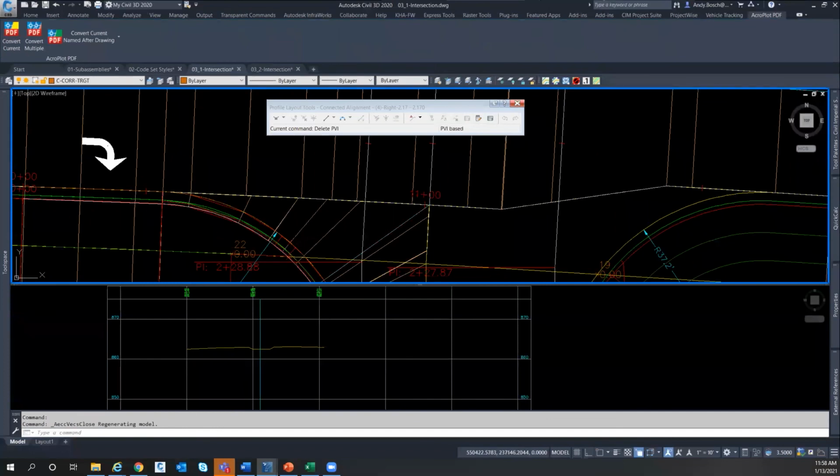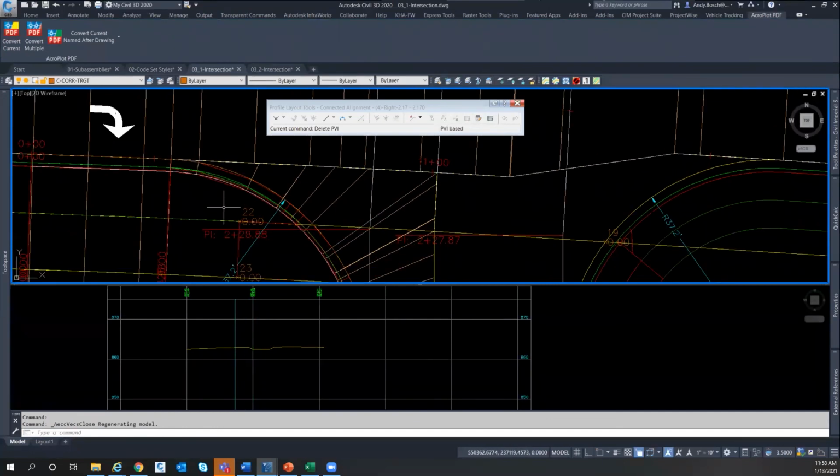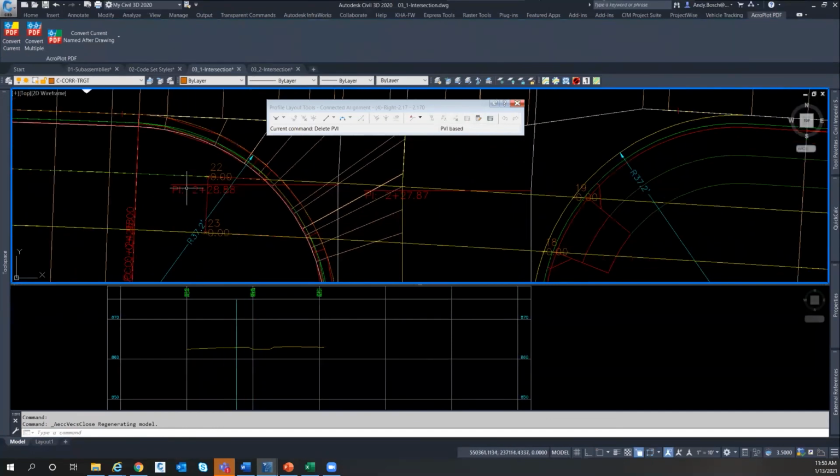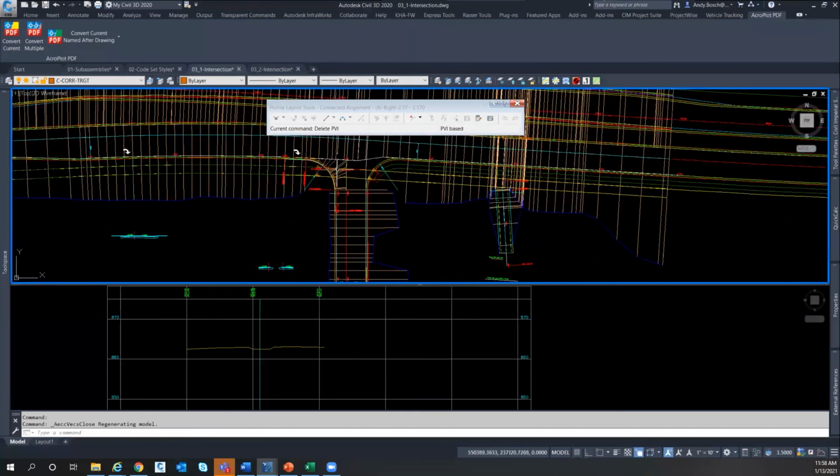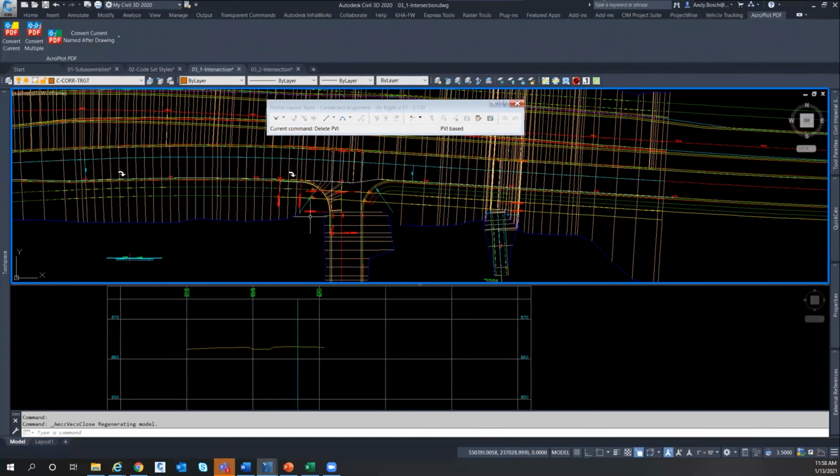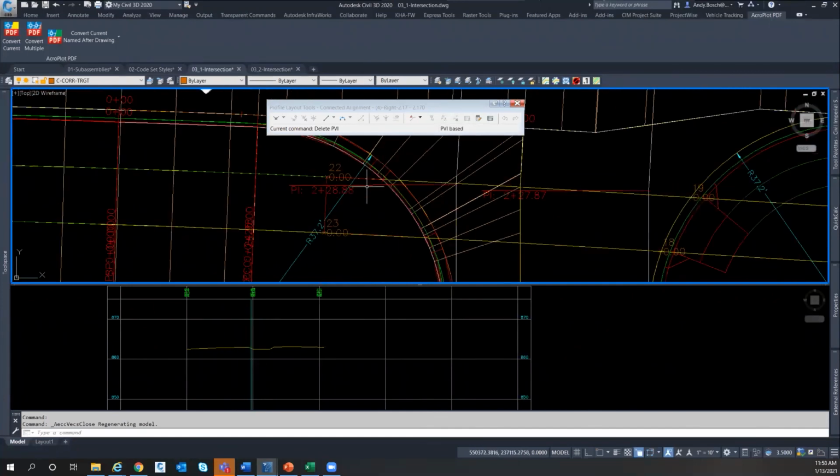Now, I was planning on getting into more details on this, and like I said, I'm up against time here, but I'll describe that I will go through sometimes the effort of modeling out these ped ramps kind of in this manner here. For this instance, when you go linearly, I'll define alignment at the front and the back. Again, I'm sampling these given surfaces so I know where I'm targeting to. I'm projecting points like I did down here, just to make sure that I know where things are at. And then I can start adding my profiles to this.